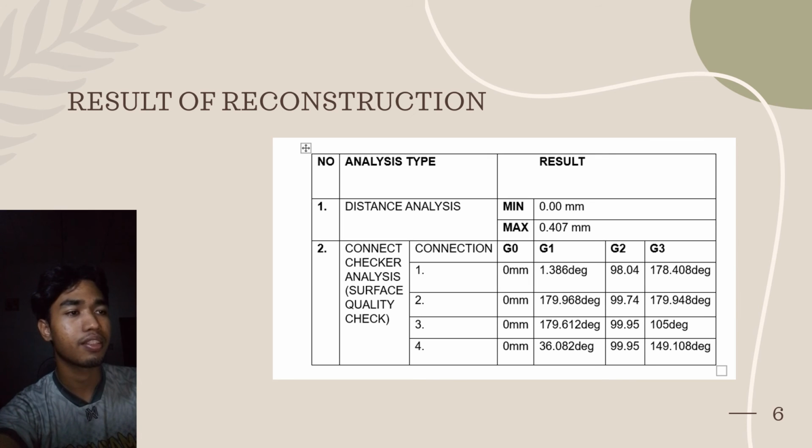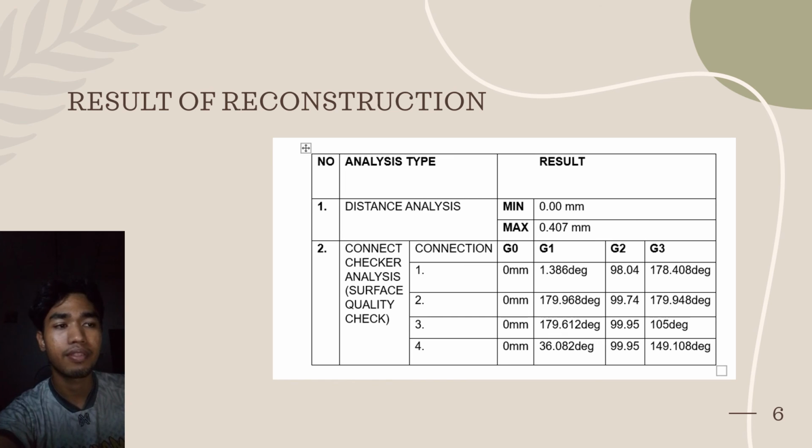The findings that we get show different levels of surface smoothness and continuity. As a suggestion for improvement, maybe I can improve the joint continuity where low values exist. Maybe you can also verify the G3 smoothness and adjust it if required, particularly for high quality surface finishing in automotive and design. If not, we can readjust the surface using trim, join or healing tools. But at least we can use another analysis in CATIA to inspect the smoothness.